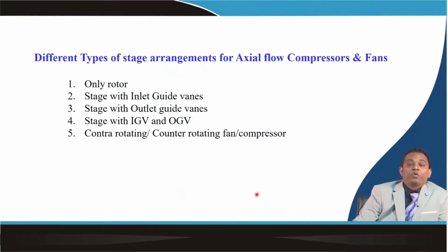We are more interested in different kinds of configuration, what we call stage configuration, which is applicable to your fans as well as compressors. What are the different configurations? We can go with only a rotor configuration. We can use a stage with inlet guide vanes.